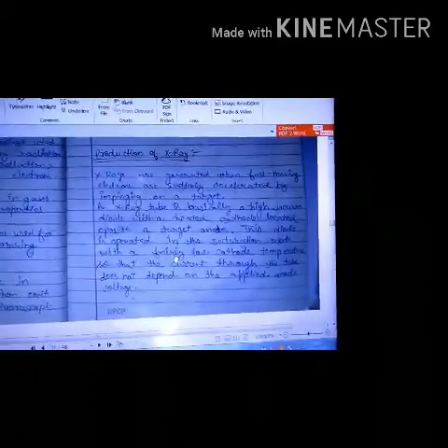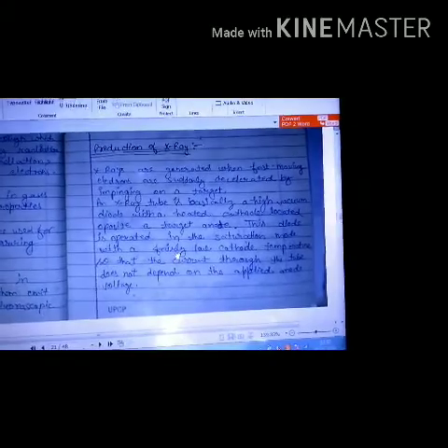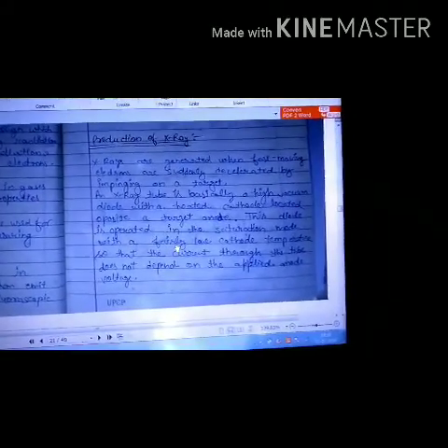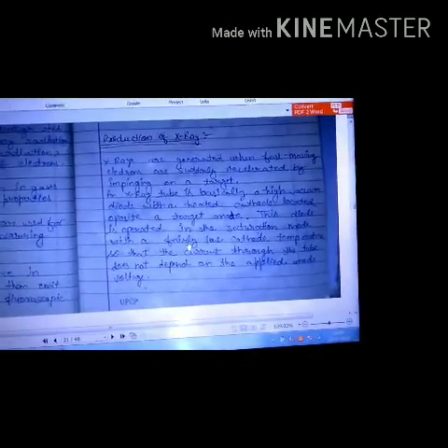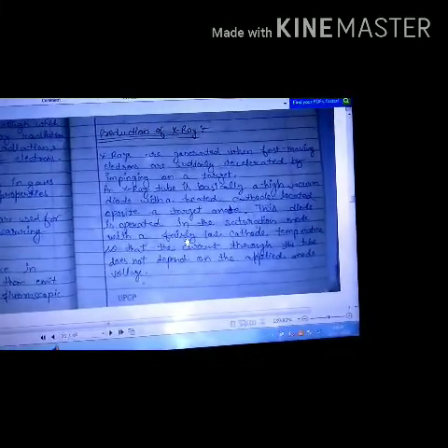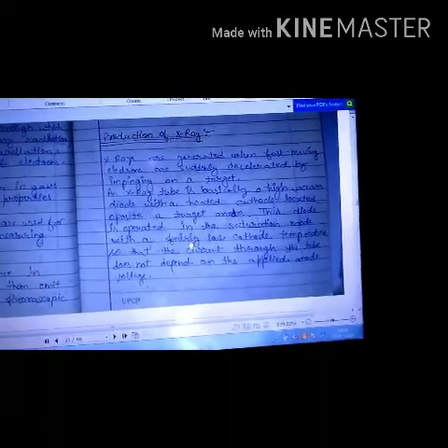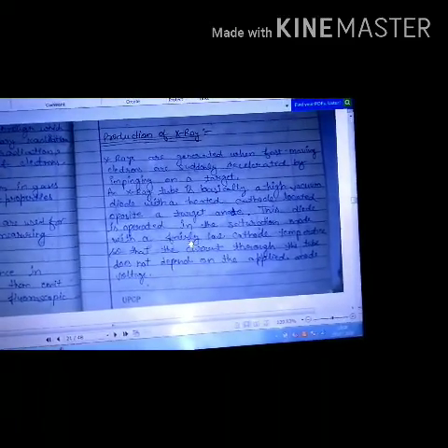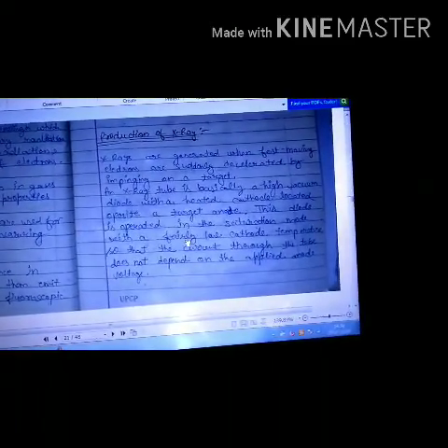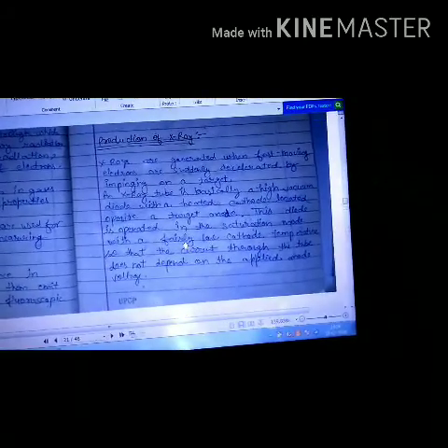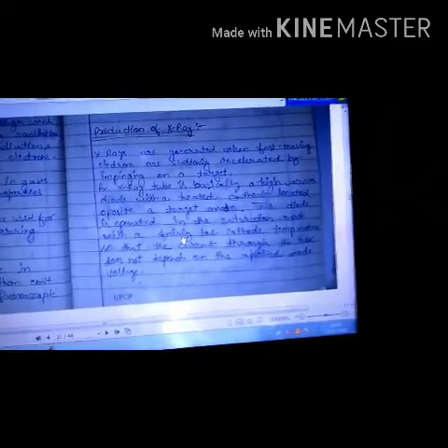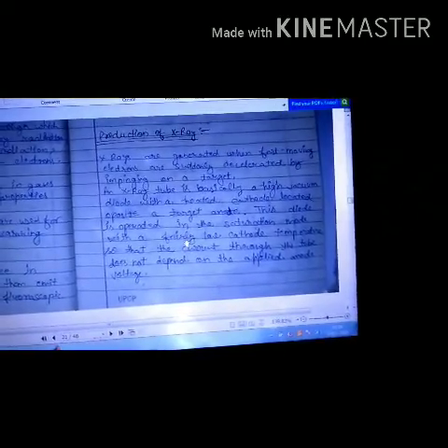Now X-ray tube is basically a high vacuum diode, a diode with a heated cathode located opposite to the target anode. So we have a target which is normally the anode, and the complete assembly is in the form of a cathode ray tube, you can assume it. Okay, and it is completely in vacuum. Now at the cathode side there is a heater which is required for production of electron beam, and at the anode side there is a target on which the electron beam can hit.